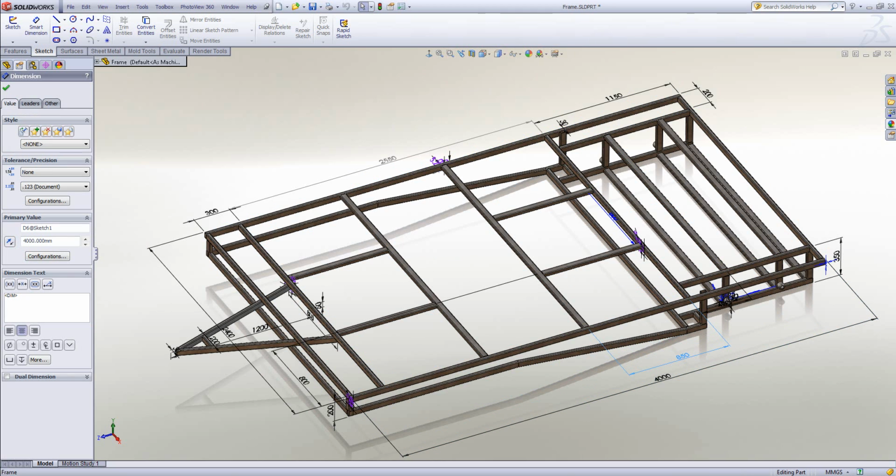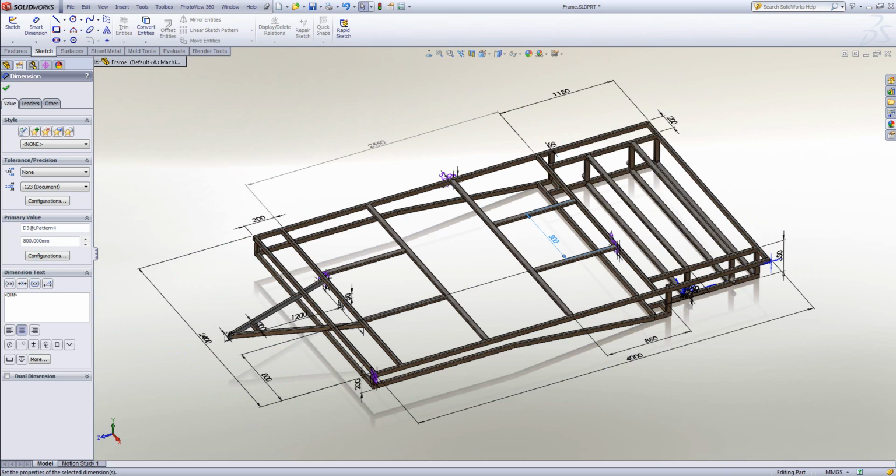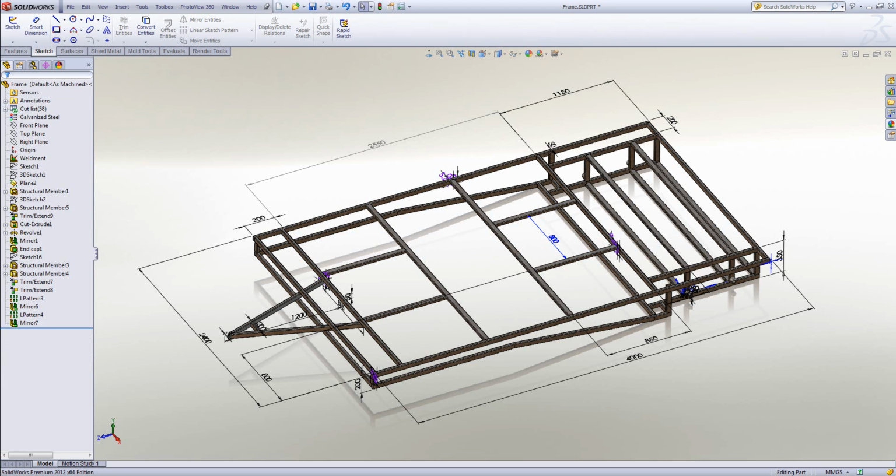Okay, so we can see the change coming through there, and I'll just drag out those dimensions that I'm likely to use over and over again. So the ones I'm pulling out are just those ones that I'm likely to use within this model to build up the changes that are going to come when I build the equations. One of the other things that's quite useful is turning on dimension names so that we can differentiate between the dimensions. If you go to the View menu, you can do that. Okay, and then we have all the dimension names appearing in the design.